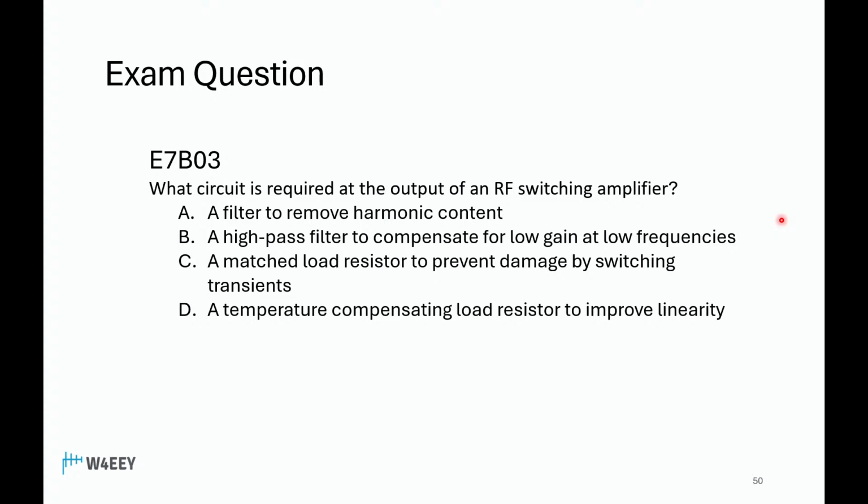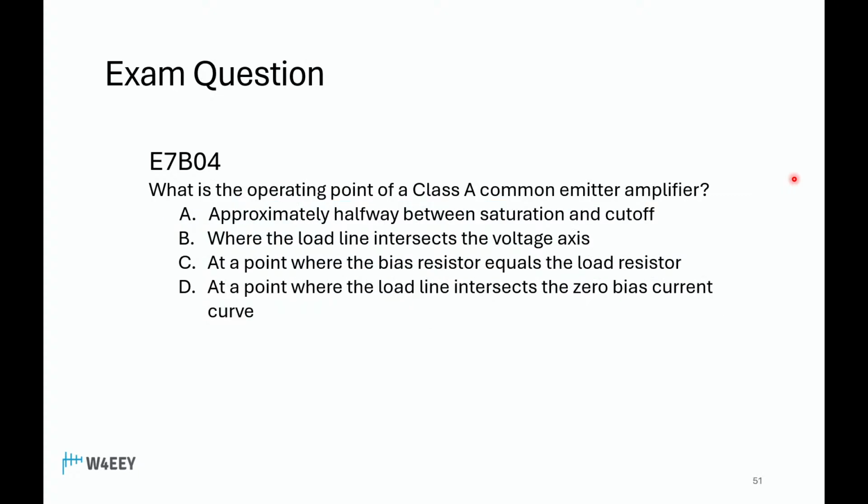What circuit is required at the output of an RF switching amplifier? A. Yep, got to remove that chopped up looking output, filter to remove harmonic content, smooth it back into a sine wave or whatever was coming into it.